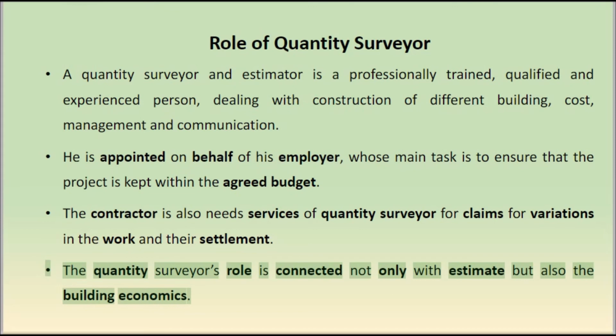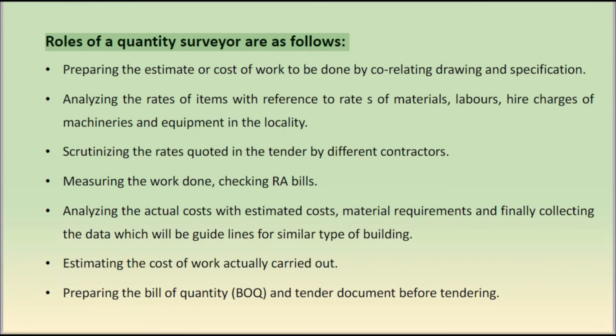Roles of a quantity surveyor are as follows. Preparing the estimate or cost of work to be done relating to drawing and specification. Analyzing the rates of items with reference to rates of materials, labor, hire charges of machinery and equipment in the locality.